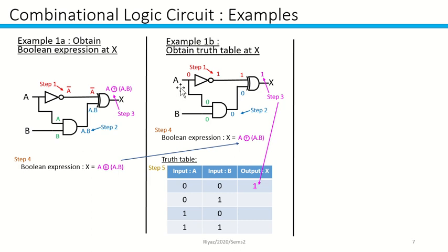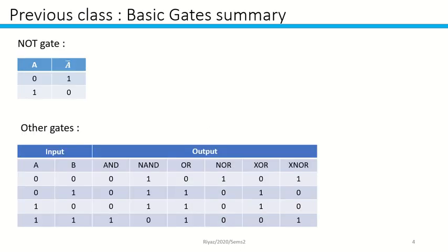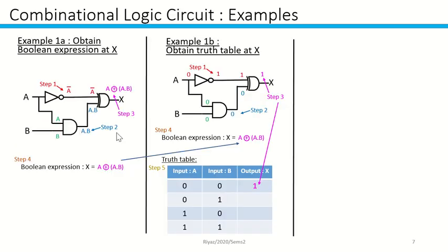In this case, when you run 0 0, you have your first 0 over here. The first step is to run over the NOT gate. If you have a 0 over here, it becomes 1, and you return 1 over here. Over here is still 0, so the 0 goes down to the green. There will be a 0 over here, and B is also 0, so you have 0 0. When you go down to the AND gate with 0 0, the answer will be 0. So that's why you have a step 2 of 0 over here.